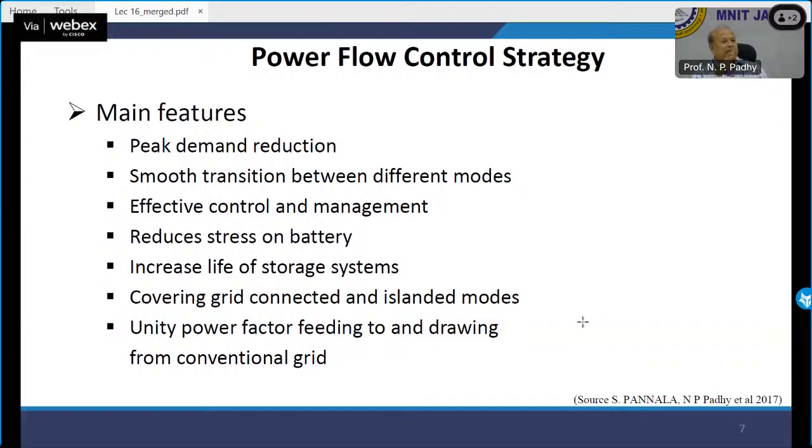First of all, you made 70% PV and all of that 70% is not cooperating. So you have to have a huge amount of reactive power. How do you get that? You don't have synchronous machines in place. Thermal power plants are not there. Nuclear power plants are not there. So it is very important to have a broader condition. I think in India, even today, I'm not very sure, is there any restriction? I think we are slightly flexible, but there must be a restriction if you are putting up a PV plant privately. Today I think we have 0.95 and above, but it should be made unity power factor injection and withdrawal.